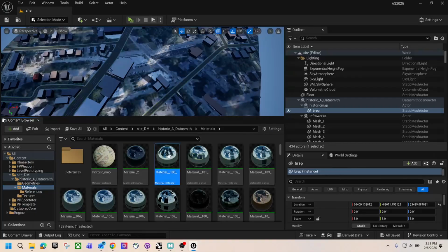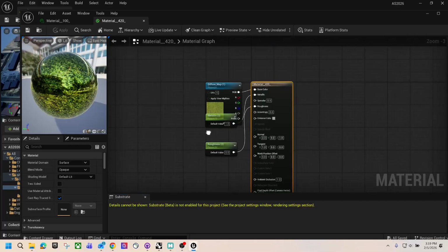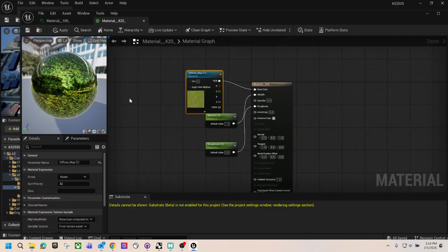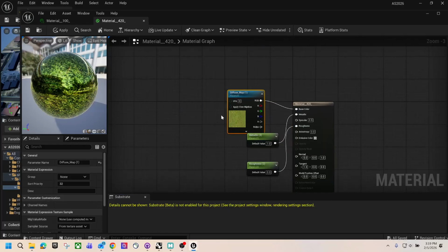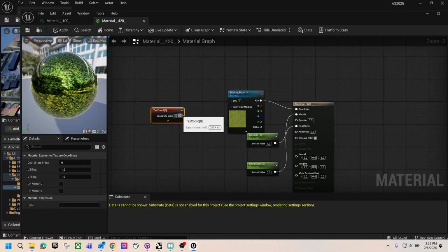Datasmith format. If I double click, it is the children of this parent, right? So you have hundreds of children all pointing to the same parent. If I open this parent, you can see this parent does not have a UV control. So here if I type U and left click, I can plug a UV control into this parent, and then by default it is 1 1, right?